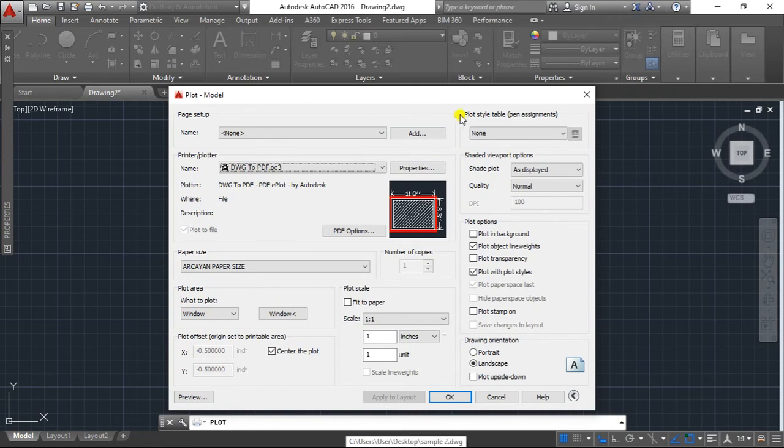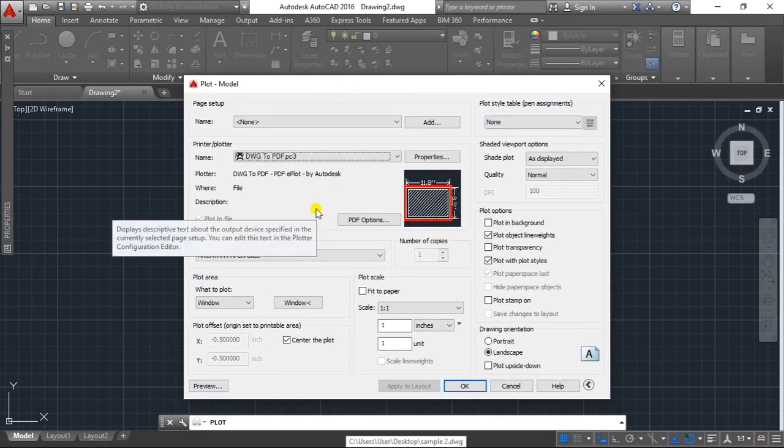So ito yan sa AutoCAD class. Now, di ba sa previous lesson, I discussed yung sa layers, pati na din yung line weights. So kapag meron ka ng default na line weight doon sa drawing mo, kung i-check mo tong plot object line weights, yun na yung makikita mo sa preview. Let's say, yung line weight mo sa object line is 1. So sa preview, makapal din yun. Now, kapag hindi ka nag-set ng line weight dun sa drawing mo, yung default niya yung susundin. Default, I think, is mga 1 mm.